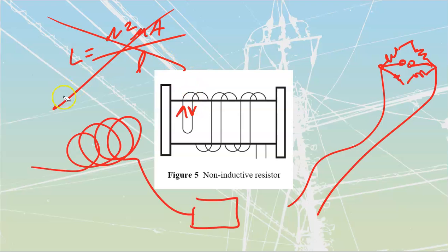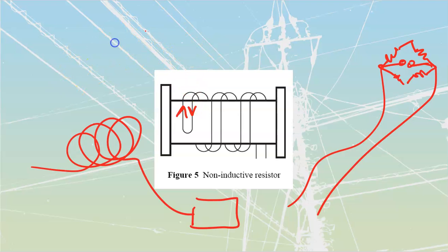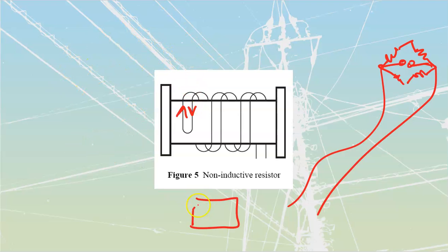We use the same concept as what we see here on the wire-wound inductors anytime that we would be dealing with instrumentation cable. We've got our cable, we'll run it all the way along, we'll work a loop towards the middle of it somewhere. Then you're just going to take that loop, push it out, and fold it in half.